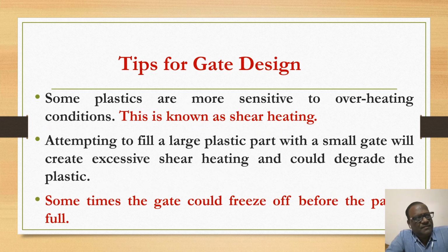Some plastics, because as already told you, the type of plastic material sometimes will decide what type of gate you have to use. Some plastic materials are very much sensitive to overheating, and that type of situation is called shear heating.